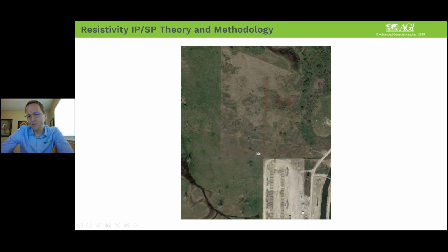So it would have been much better if they had maybe run one over here, and done some different line placement. It looks like there's quite a bit of space here, so they have other options. The voltage itself is not an issue. Typically, unless there's a lot of leakage from those overhead power lines, there's EM filtering, 50, 60 hertz filters, and in the duty cycle of our instrument, we cancel out noise. So the EM noise from these AC power lines is not an issue. It's the grounding between the towers. So you don't want to be parallel to them.